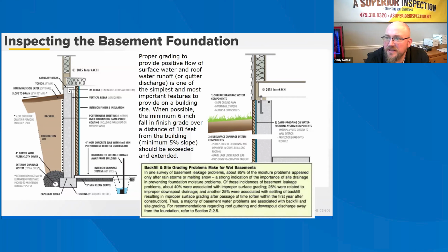Foundation drainage serves several functions, such as removing free water from the foundation perimeter, which reduces lateral load on the foundation wall. It also lowers the groundwater level around the building's footprint, especially during wet seasons. Basements should not be used where groundwater levels are near the basement floor level. Current model building codes require drains around all foundations enclosing habitable space, such as basements, unless soils are naturally well draining.